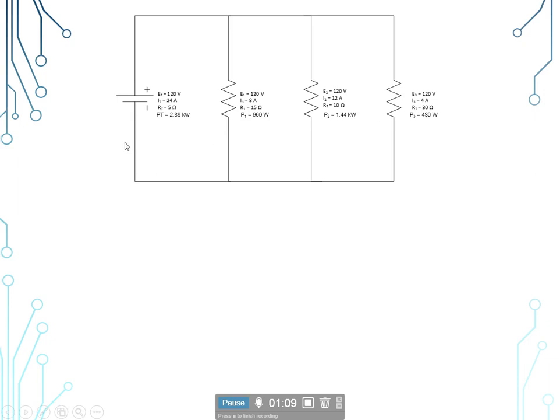Now we'll be using this parallel circuit. Remember, this is the cell symbol that we're using as a battery to save real estate. Remember, the longest bar is always positive and the shortest is always negative. So always pay particular attention to how that cell is put in there. If you remember from the series circuit, I have flipped the battery over in this case. Then we have our first load here. Remember, that's a resistor symbol. We have our second load here and our third load here.